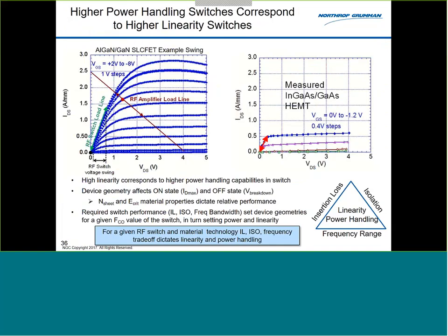Right here. Okay, so on the plot on the left, I actually show, this is a 6-channel device, but here I'm showing it in 1 volt steps. So I'm showing when I have the gate at 1 volt and 2 volts on the gate, the top 2 blue curves, and so you can see this additional current that I'm getting.